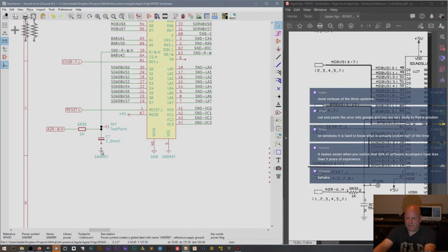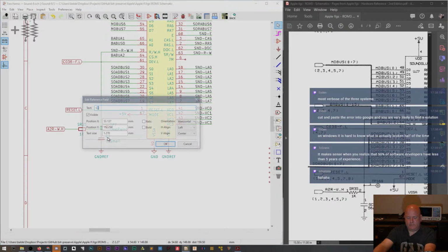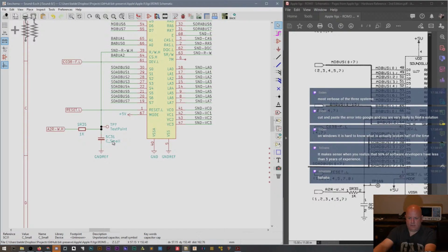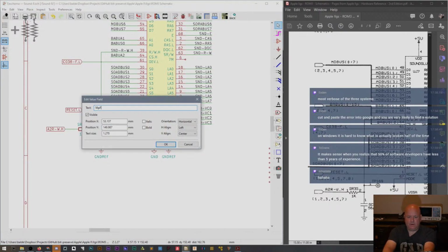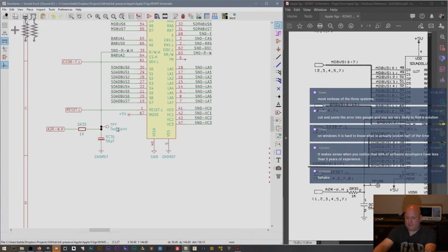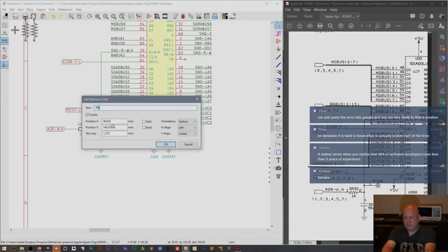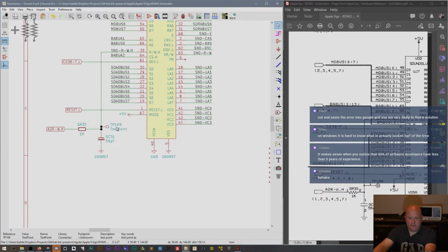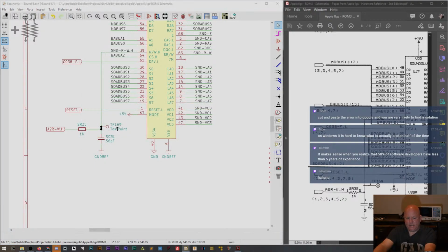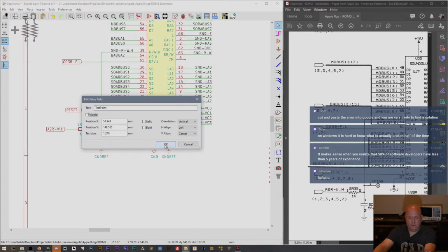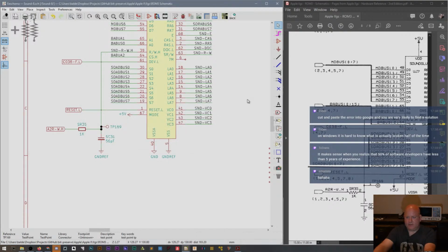That's interesting, that's not the digital ground. Use wire, come to here. Okay, this will be SC31, and it's going to be 56 picofarads. And this test point is TP169, and then I'm going to hit edit on there to bring up this window, hit visible to make it go away. And so now that looks a lot more like the schematic.